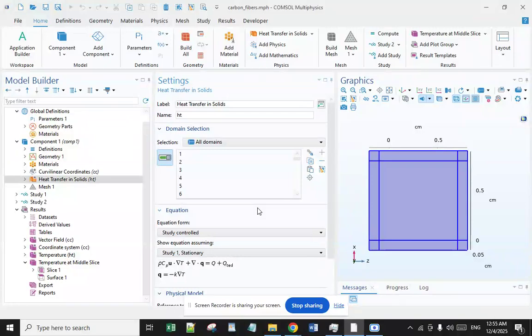According to the material specifications, the polyester stitch has a glass transition of 80 degrees centigrade and a melting point of 260 to 270 degrees centigrade, and the binding agent has a melting point of 110 degrees centigrade. No endothermic effects indicating glass transition of the stitch or melting of the binder are visible in the DSC curves, which may be due to the fact that the amounts of binder, below 5%, and stitch in the sample pan on the DSC instrument are negligible in their effect on heat flow.